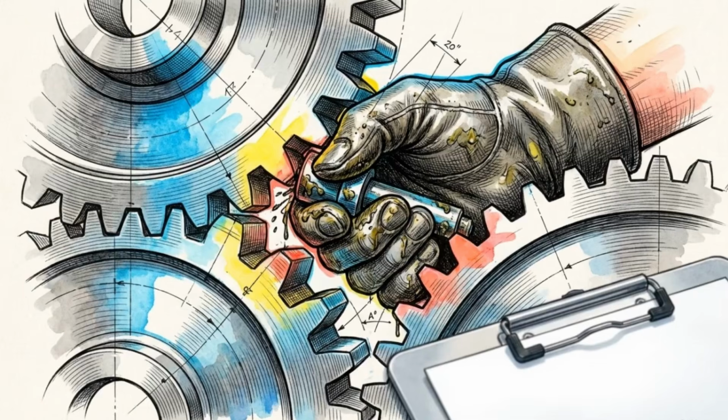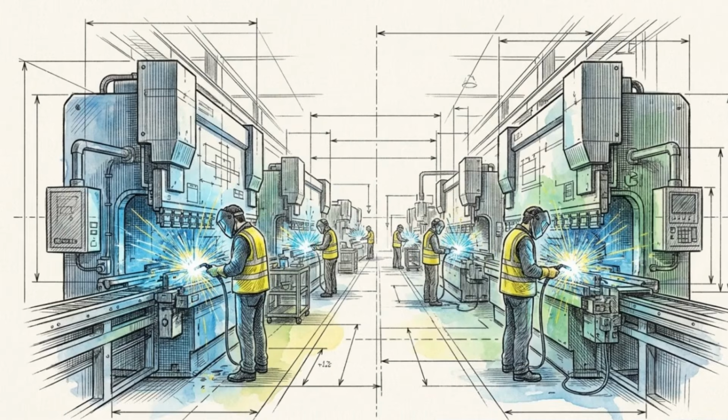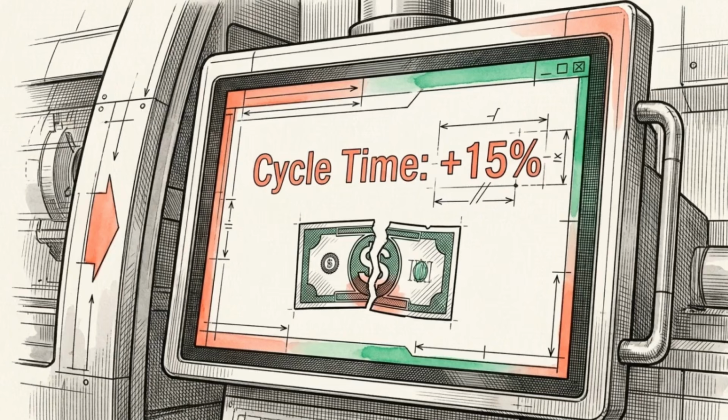Watch the machines closely to spot the silent killers of performance, tiny recurring 2-second microstops that operators resolve without ever logging them on a chart. These specific losses are highly deceptive. The floor sounds loud and looks busy, completely masking the reality that cycle times are stretching and money is being wasted.